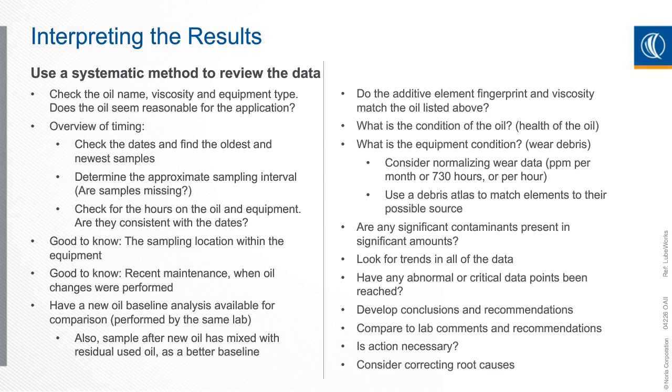How is the condition of the oil, the overall health, the remaining useful life, looking at the oxidation levels, whether or not you've been able to test with linear sweep voltammetry or RPVOT or acid number, viscosity. All these things can help determine what the overall condition of the oil is. How is the condition of the equipment? Of course, that's wear debris, for example. And you want to normalize that to your run hours.